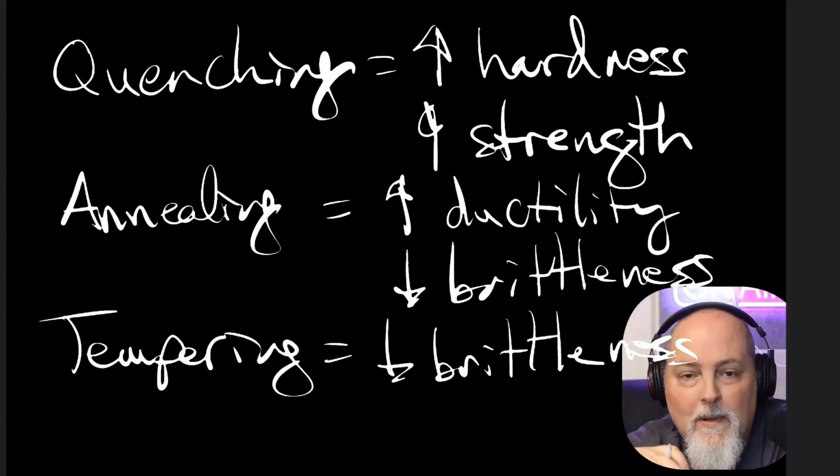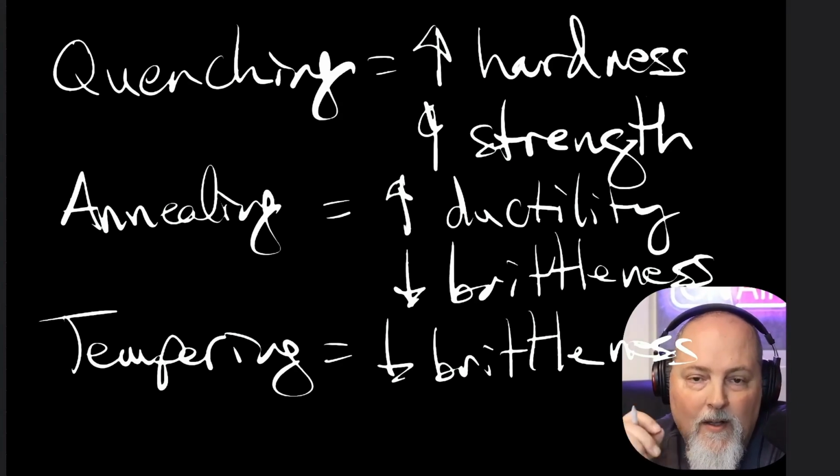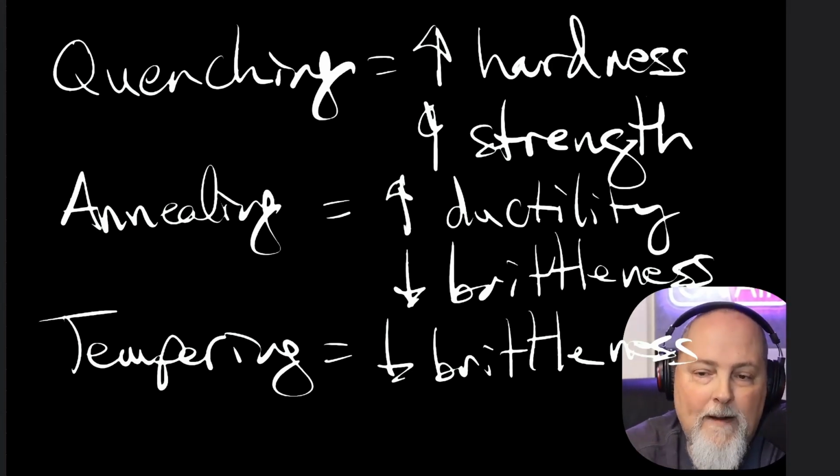grow inside the metal. All right, welding is another topic because it can damage material if it's not controlled properly. Welding causes localized heating and cooling. It introduces residual stress, distortion, can cause things to crack or create a later cracking risk. So the common adverse effect is residual stress formation.